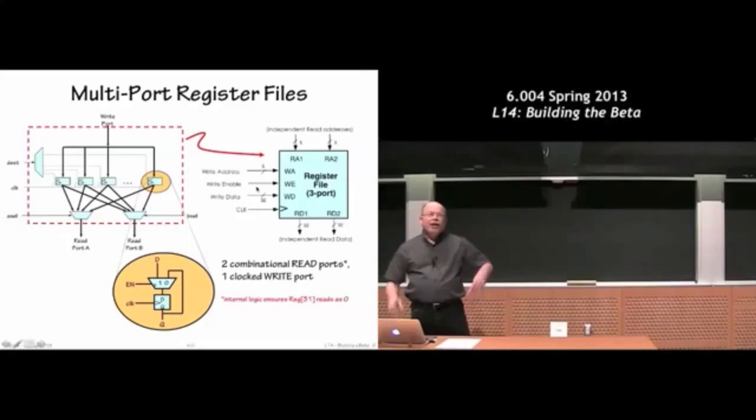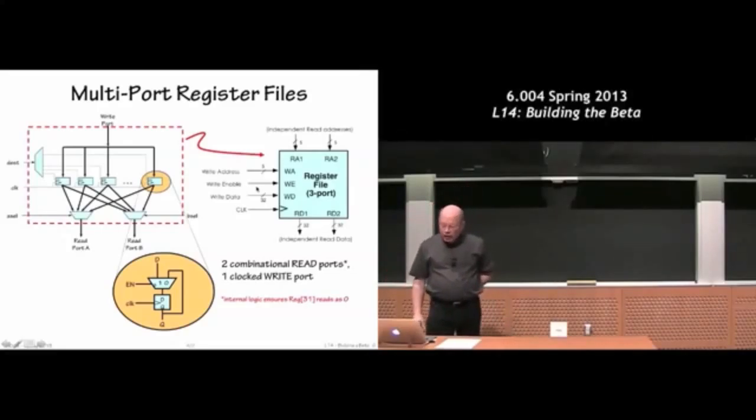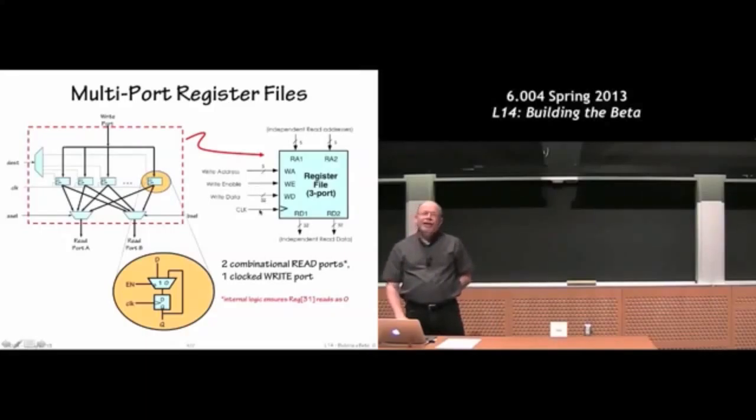So that's another control signal that says that the 32-to-1 decoder we had, or the 5-to-32 decoder, that selected which enable signal to produce to write into the register, to pick a register to write into, we can just disable that logic altogether. I'll say more about that in a second too. And then the write happens at the rising edge of the clock.